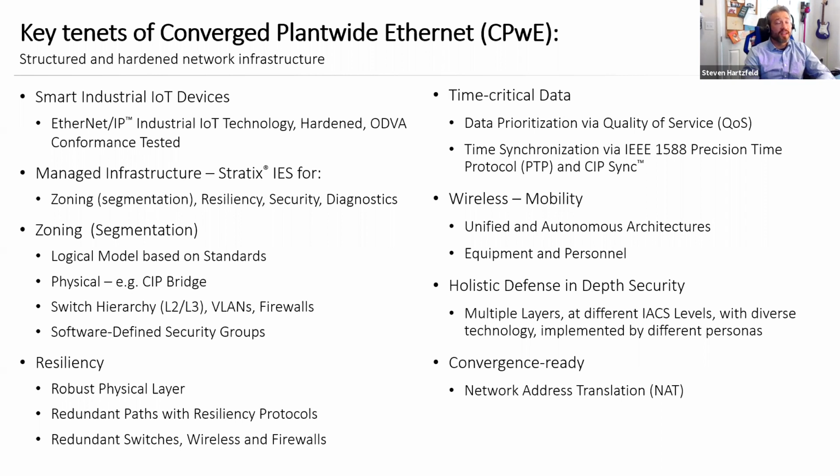And one of the nice things about the Stratix switches is, depending on the model, they come pretty much out of the box with a base QoS prioritization framework already deployed. So it's optimized for use in an industrial environment, knowing the types of traffic that it's going to experience, knowing which ones are typically most important. Something that an off-the-shelf Best Buy switch certainly isn't going to do.